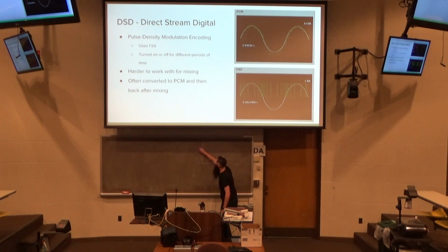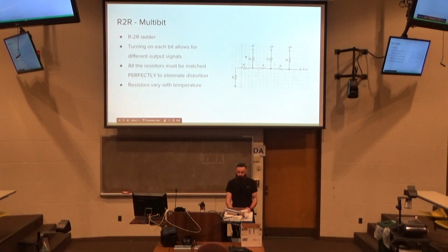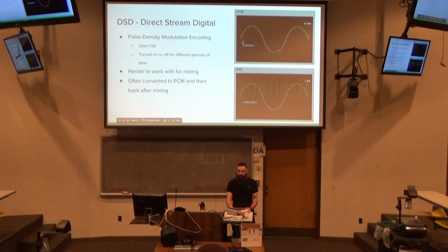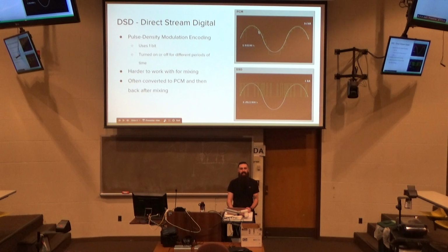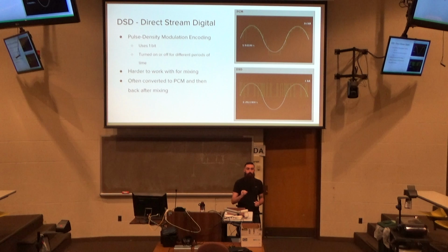This bit is literally one level. So for the people online, the binary number that we would put into these bits is the same value as is at one of these steps at any instantaneous time. And then at our sample rate, which in this case is 44.1 thousand times per second, we will change those numbers being output.